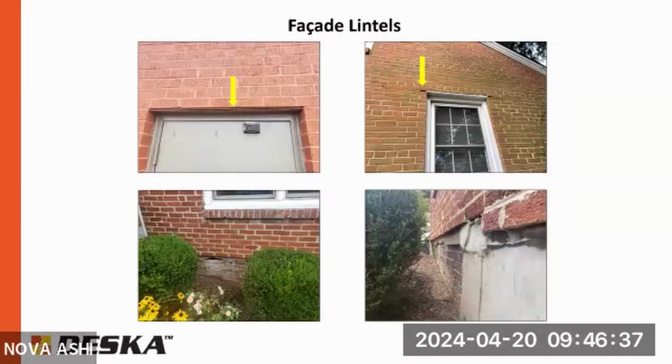If it's just that the mortar has flaked off and the lintel is visible, I would say you can definitely just have it scraped, sandblasted, cleaned and painted again, and then remortared. If it's a hairline crack, I could understand going for that. Once it's separated and it's already causing noticeable cosmetic damage, I would say it's too late. It's already expanded, it's already corroded. You could remove the two rows of bricks above it, pull the lintel out, clean it up, and then reinstall it. But at that point, you might as well just put a new lintel in. Most of the work is in the masonry and getting it out.